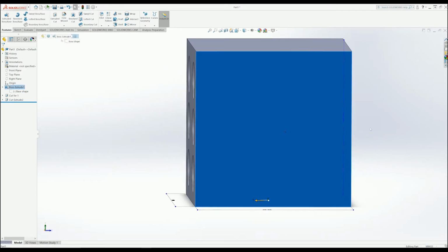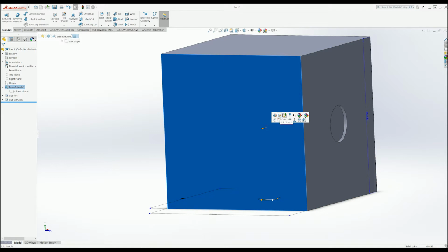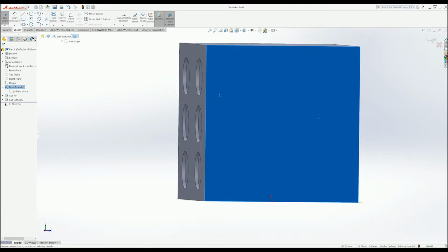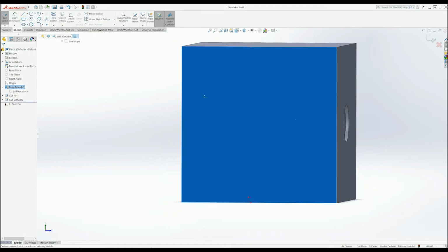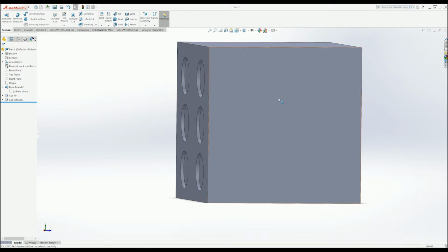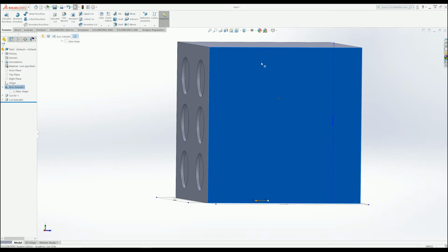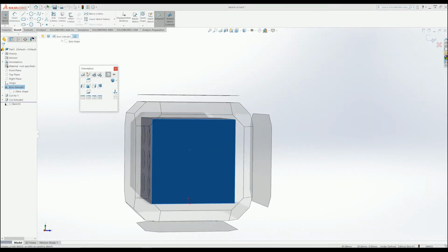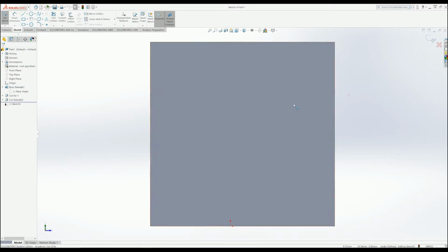So we're going to move here. Let's go number 4. Let's go 4 on this side. So again, I'll just show you that bit, just to remind us. So click the surface, click it once, you get this menu appear, click sketch, spacebar, normal 2. Nice easy steps for us to follow.